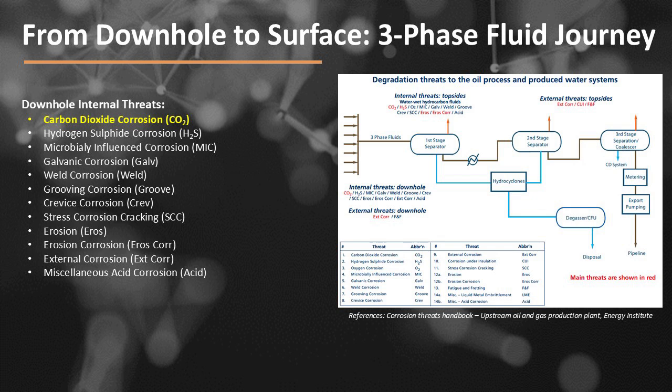Number 7 is crevice corrosion, happens in shielded areas like gaskets, flanges, or under deposits where stagnant fluid allows aggressive ions to concentrate, leading to rapid localized attack. Number 8 is stress corrosion cracking or SCC, a dangerous form of corrosion that combines tensile stress and a corrosive environment, leading to sudden and brittle failure without significant deformation.